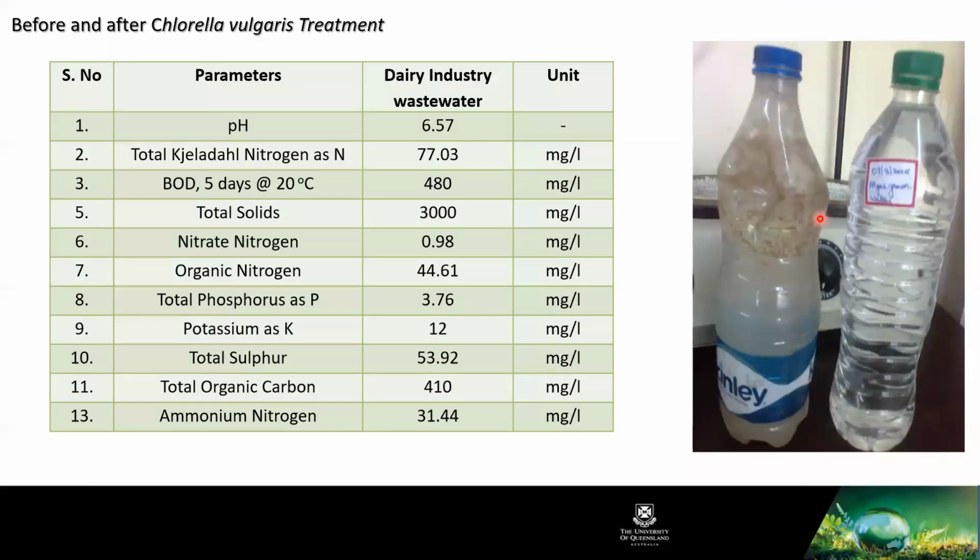I told you we even tasted this clear water. It's nearly like drinking water. So the effluent was like this. It was treated with Chlorella vulgaris, and after the treatment became like that. So we just removed the biomass, I mean the algae, after it grew to a certain cell density, and then used a flocculation method to remove the algae. So this is the pure water, nearly drinking quality.